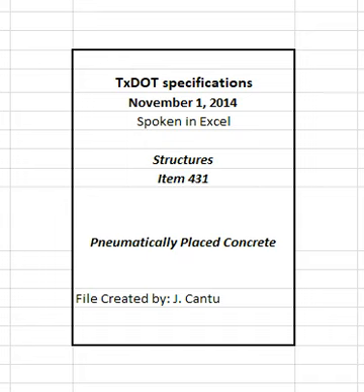Maintain steady pressure throughout the placing process. Use a water pump with the size and capacity to deliver water to the nozzle with a pressure at least 15 psi more than the required air pressure. The values shown in Table 2 are based on a hose length of 150 feet with the nozzle less than 25 feet above the delivery equipment.